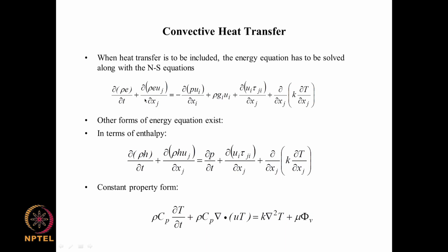So this is associated with the flow. The fact that flow is coming in and going out of the control volume brings with it anything that the fluid possesses, including the x momentum, y momentum, z momentum, internal energy, enthalpy, entropy, concentration, all those things are brought in, and this is the net thing arising out of the coming in and going out of the flow through the control volume.